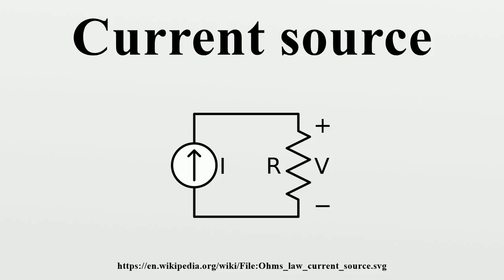When this current through R_sense to ground is sufficient to cause a voltage drop that is equal to the VBE drop of Q2, Q2 begins to turn on. As Q2 turns on, it pulls more current through its collector resistor R1, which diverts some of the injected current in the base of Q1, causing Q1 to conduct less current through the load.